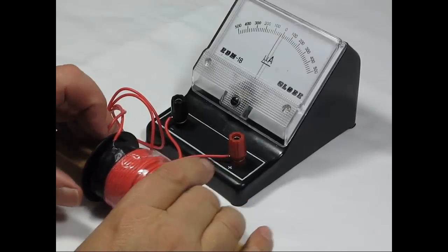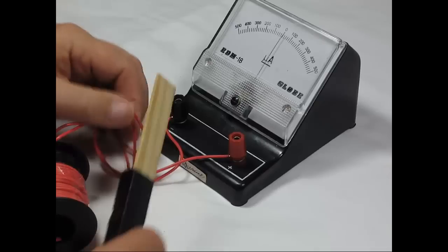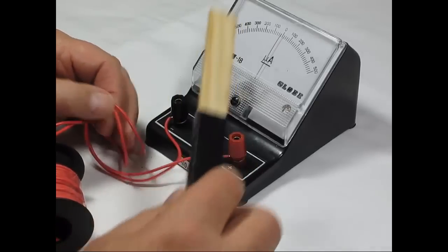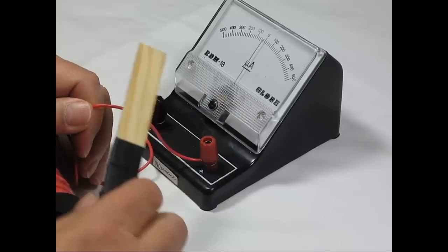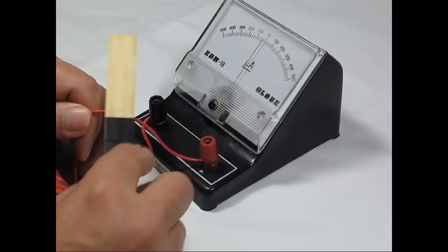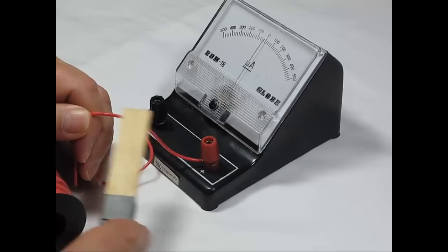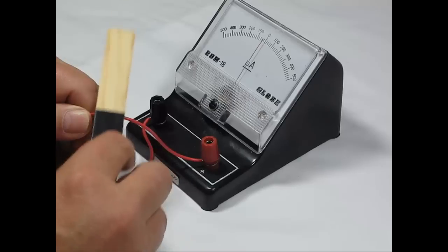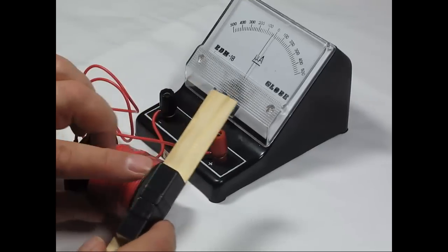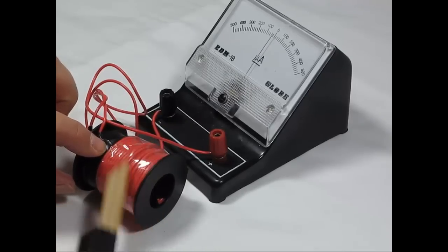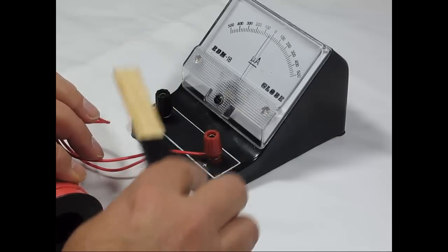Another thing I wanted to show you is, you see, when you have a big loop of wire, you get a lot of heavy action. But if I just pass it by a single conductor, in other words, if I separate out one conductor here, you see the needle motion? Because the magnet only has influence over the electrons in this small area of the conductor, so you only get a little bit of induced current. But when you do it inside the coil, the permanent magnet is influencing all the electrons on this full length of wire because it's wrapped up in a coil, as opposed to getting just a tiny little deflection on the meter from this motion.